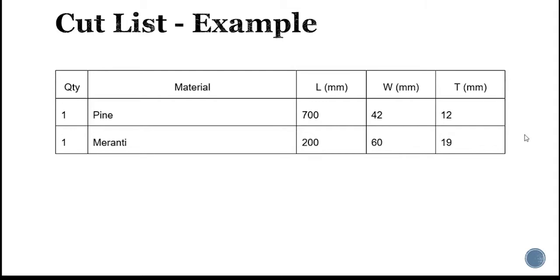If I needed 7,000 millimeters, which is 7 meters long, I couldn't do that with one piece. I might ask for instance, 3 pieces that are 2,400 millimeters long, and that would actually give me 7.2 meters. On the other hand, I can't fit a piece 2.4 meters long into the benches at the school, so I might end up cutting that down to pieces that are 800 millimeters long, in which case I'm going to need not 3 but 9 of them.